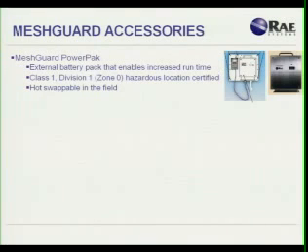You can simply take a new battery, bring it out there, unplug this battery in the hot zone, put in your new battery, and then you take your old battery back for recharging. All right, so that's really the key feature, that it is hot swappable in the field, Class 1 Division 1 Zone 0 certified.